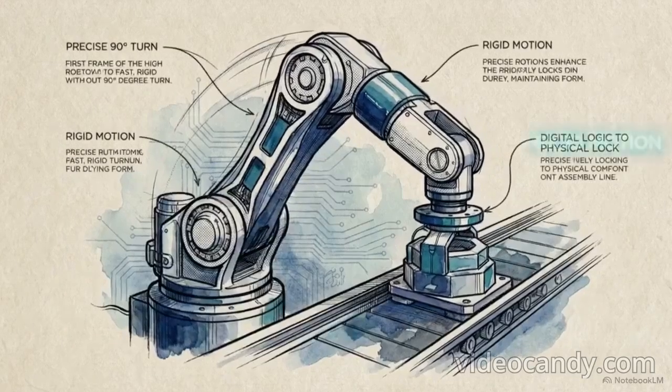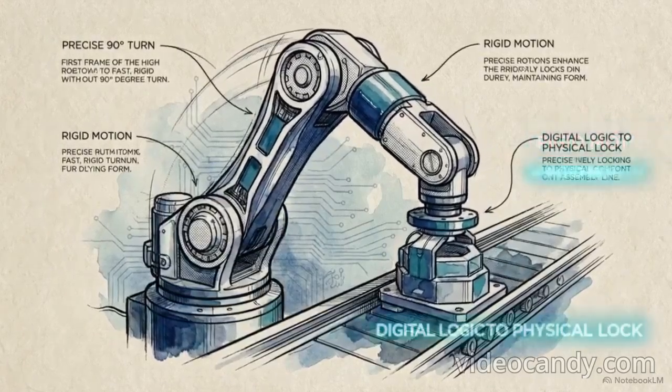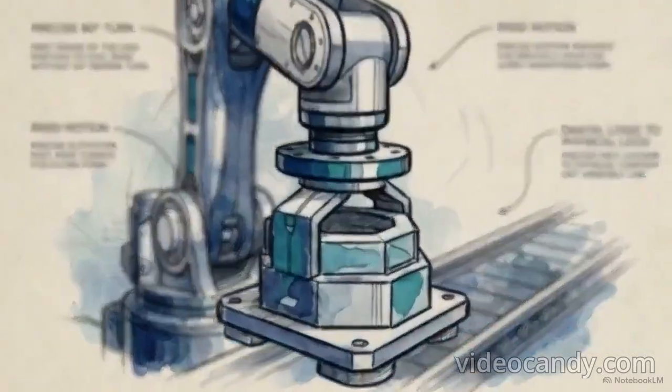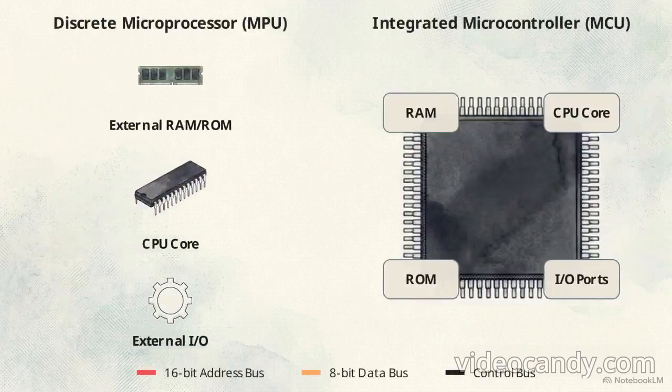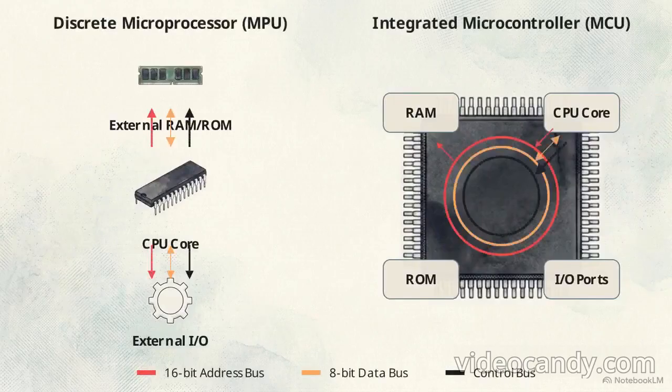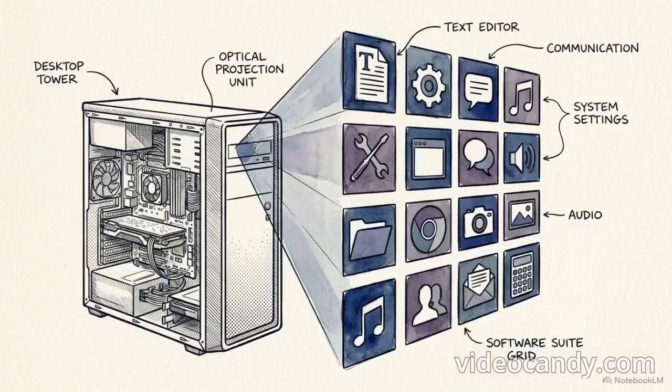When the ADC translates the analog voltage into an 8-bit binary word, it sends an end-of-conversion signal. The data then flows across the D0 through D7 lines and directly into port 0 of the microcontroller. This interface is the mechanism that translates continuous real-world conditions into the deterministic digital logic required by the core processor.